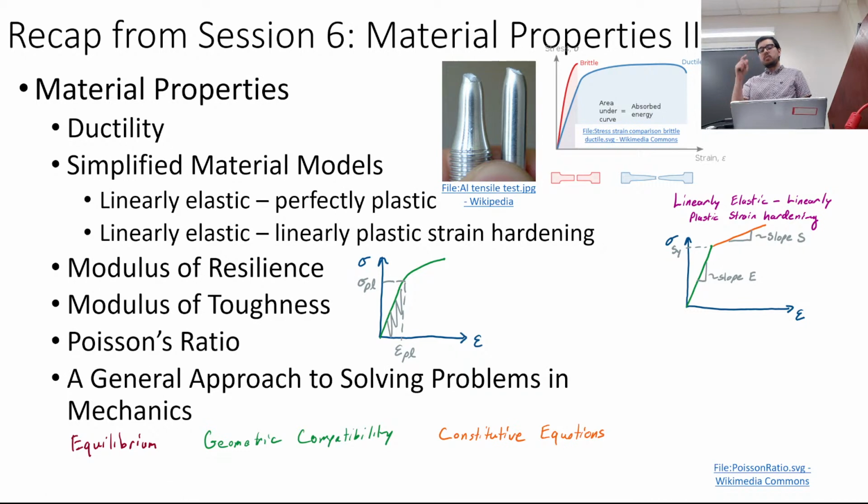Of those three, the one that we'll see come up more in the course is the Poisson's ratio. I mean, these two are very important. The Poisson's ratio ends up affecting how we look at strain. And as we look at 2.5D problems, as you've already seen, it affects the amount of contraction or expansion we have in a member as it's axially loaded.